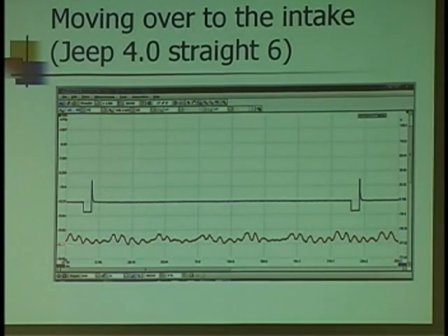Anything stand out for you? Flat spot. Well, here's one right here. One right here. This one here, did everybody agree this little section here kind of looks like what I would expect to see normal? Yes. Because it's pretty repetitive. Not always the same amplitude, but the 2, 3, 2, 3, but these little flat spots here, that's an issue.